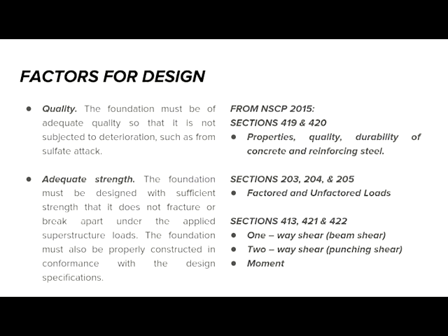We have covered it already on your construction materials subject. Next, adequate strength. The foundation must be designed with sufficient strength that it does not fracture or break apart under the applied superstructure loads. The foundation must also be properly constructed in conformance with the design specifications.